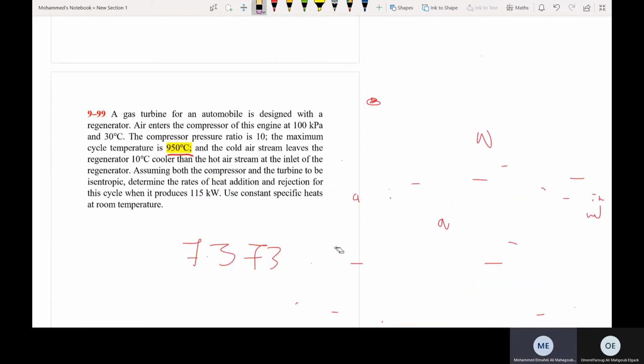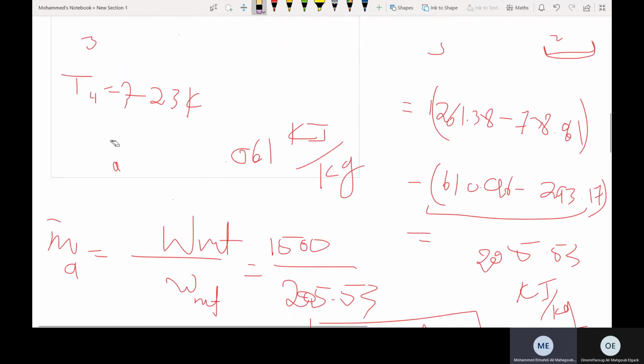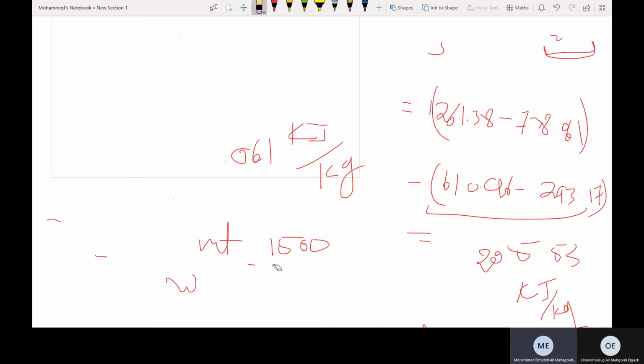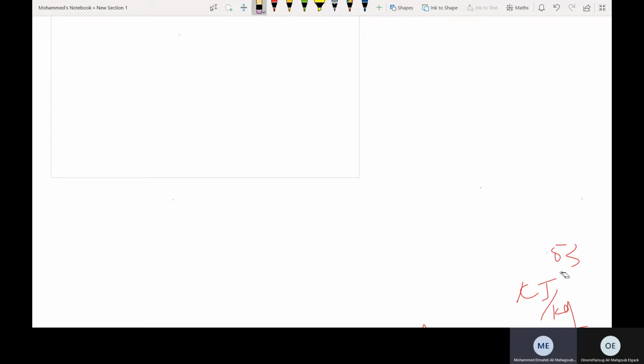So yeah. Now, this is the problem with the regeneration. The Brayton regeneration cycle is also a modification of the Brayton, where we make some utilization, but this utilization will be inside the cycle. So it will affect the thermal efficiency of the cycle directly. Why? Let's see how. This is one with the cold air assumption, so you get used to both approximations or both assumptions for air. Sorry for taking time to delete this.